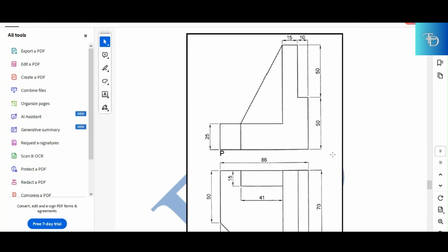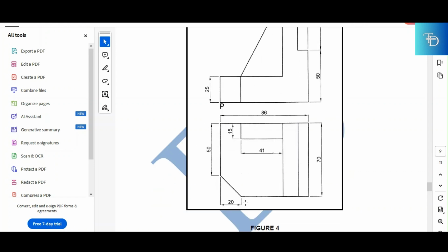And then the length of the drawing from the side, it's 86, which means this side is 86 long, and also this side is 86 long without subtracting the 20. So since you know that the whole side is 86 long, and then on this side you have a 20 millimeter chamfer there, which means 86 minus 20 millimeters, you are left with what? With that dimension right there, with the missing dimension. That's why they didn't give you that dimension, because they want you to calculate.